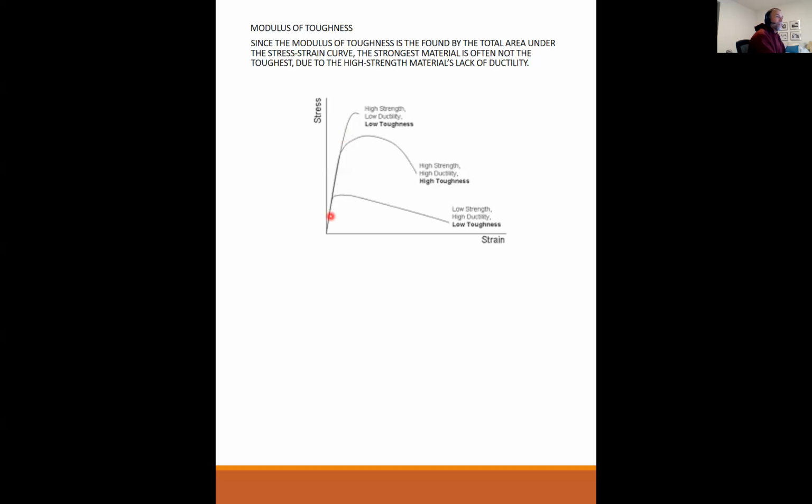On this chart here, here's 60, here's 270, but the material is very brittle. So it would follow a curve just like this, and then it snaps, it just fractures. So each individual wire in the strand has low toughness. It would not do very well at all.